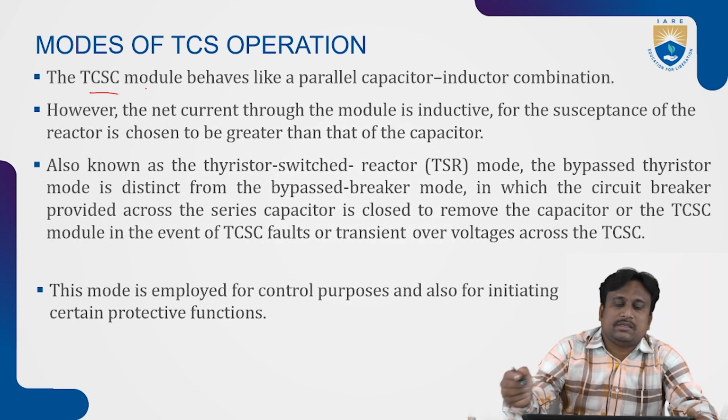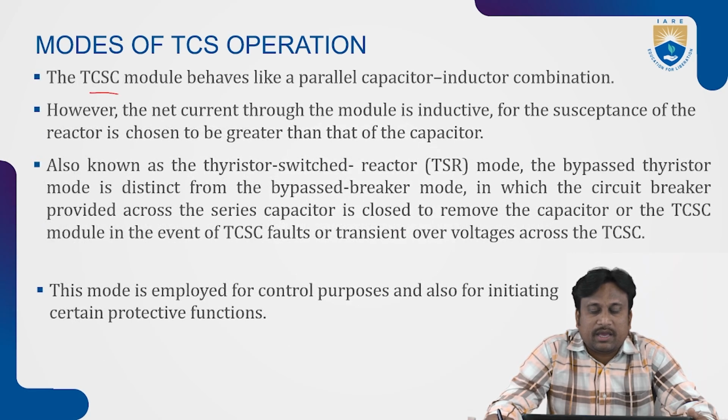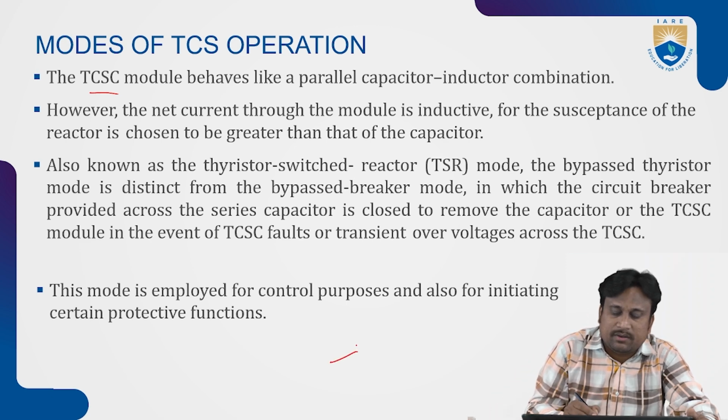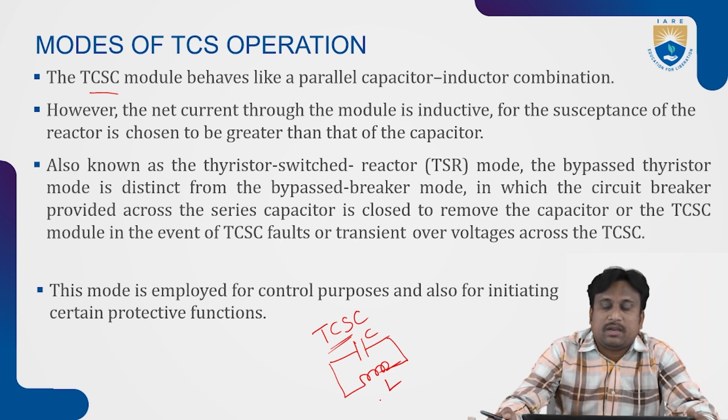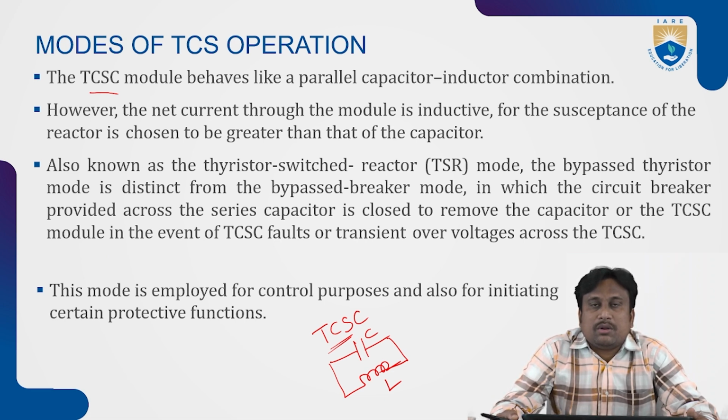So here the TCSC module will act like a parallel capacitor inductor combination. However, the net current through the module is inductive in nature, so the susceptance of the reactor is selected to be greater than that of the capacitor.